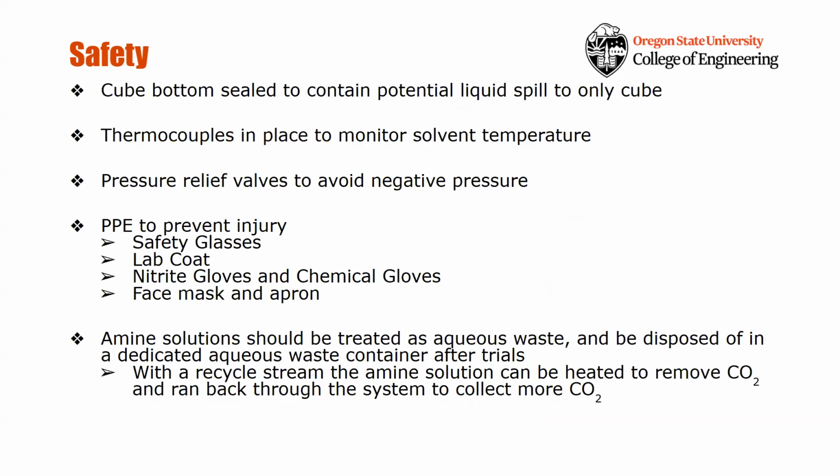The safety will mostly revolve around the amines that are going to be used. The cube bottom will be sealed to contain any potential liquid spill to only the cube area, such that we don't have a widespread spill cleanup. Thermocouples will be in place to monitor solvent temperature, especially since this is a sealed system. That'll be critical to prevent overpressurization. And in addition, pressure relief valves will be there to avoid the negative pressure pitfalls since we'll be using a vacuum.